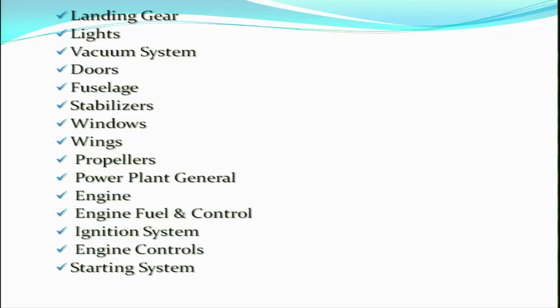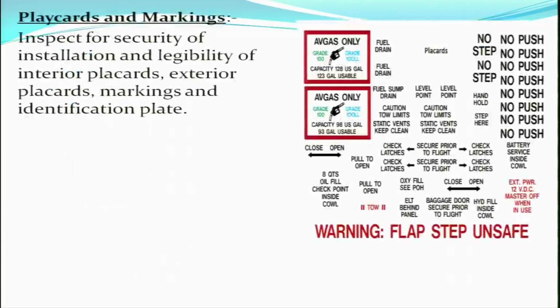The 100 hours inspection is considered to be a major inspection which is carried out at 100 hours or 1 year, whichever is earlier. So we ensure that the complete aircraft is covered in the 100 hours inspection.